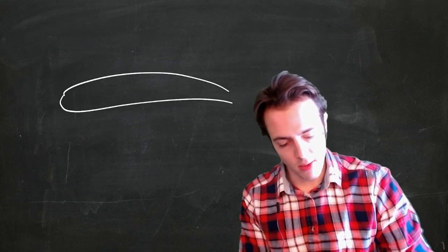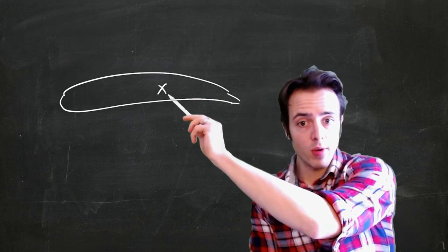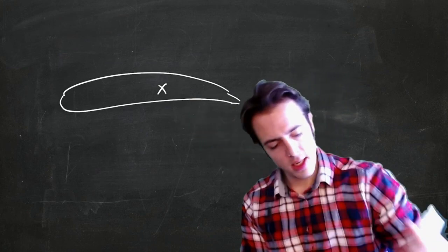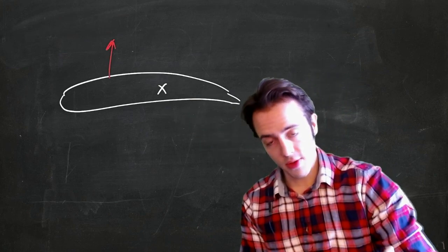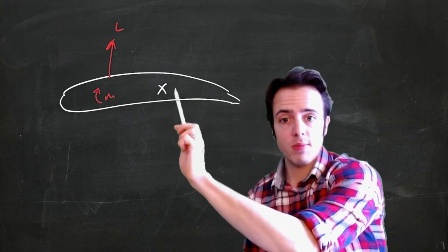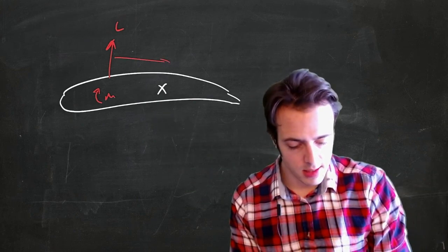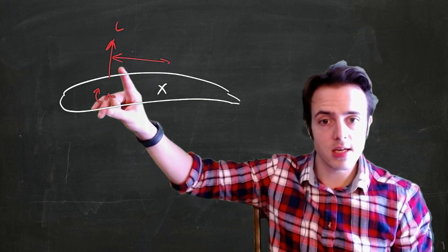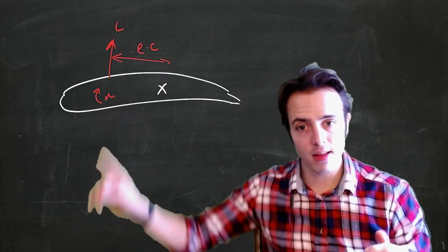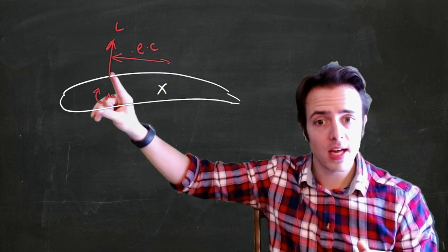So we've got a wing section like this, and we've got a flexural center, which is the shear center of this wing. And we've got then, for example, the aerodynamic center where we've got lift and the pitching moments. The distance between the flexural center or the shear center and the aerodynamic center is given the symbol EC. Okay, that's the elastic axis, where E is a non-dimensional distance denoting the distance between here and here.